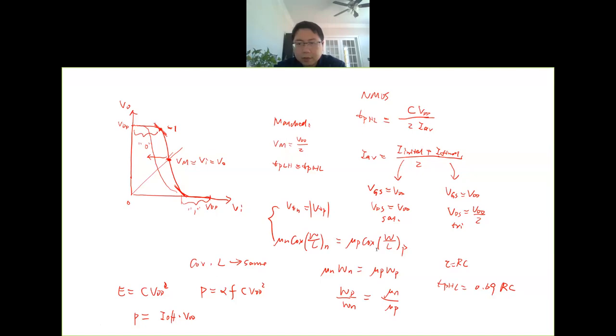Okay, so here is one question. Is it true that as long as VTP equals VTN, the circuit is matched? The answer is no. VTP equals VTN just guarantees that the point where you start decaying this output is the same, but how fast it reaches this point depends on the current.